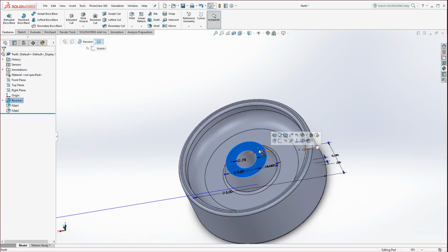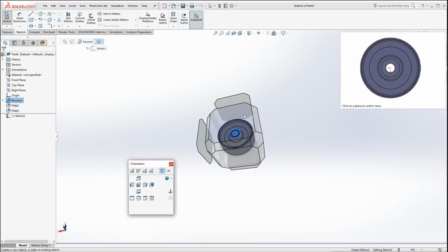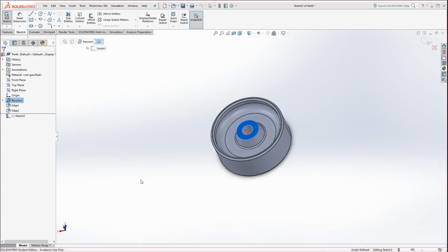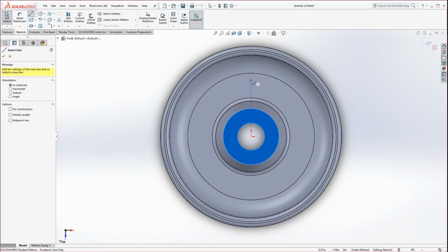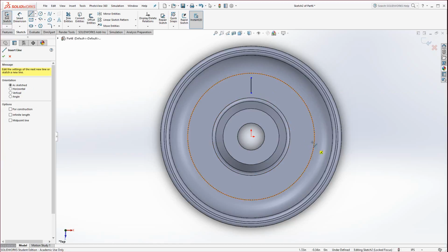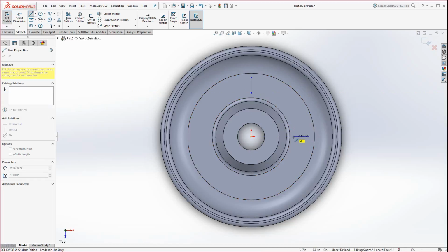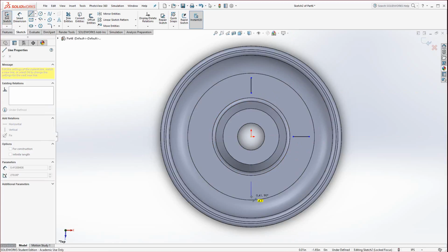But in this case, we select this face and start a sketch. Go ahead and hit your space bar and go to the top view orientation. You can either select this face or you could go to top. Now take the line tool and infer to the origin in between this little segment here. Be careful not to extend these lines as you draw them too far beyond the boundaries of the actual surfaces. You might get an error if you do that.